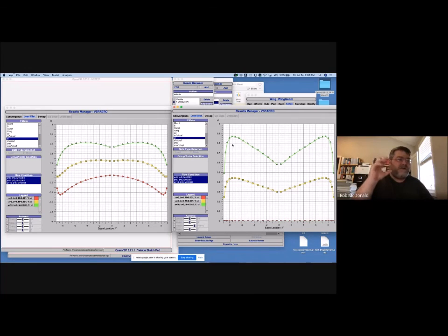So one of them is going to stall and not the other. And what that means, if it stalls on the tip, think of it as a moment arm. If one stalls and not the other, that wing is going to dump out, right? It's going to drop out from under you because you've lost lift way out on that tip. So you're in there, you're turning base to final, and you lose the lift on the tip. That wing's going to stall, and basically you're then going to tumble and you're going to crash.